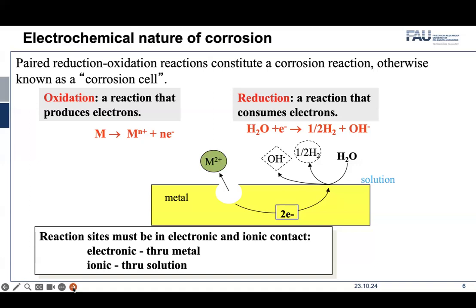There is a fixed electron source, which is the aluminum matrix that dissolves, and the fixed electron sink, that is this copper precipitate. So this is usually called a microgalvanic coupling. If we have a simple metal, maybe magnesium, then this process is totally random. Any site can act as an anode, and maybe become a cathode later on. So on the whole it is uniform corrosion.